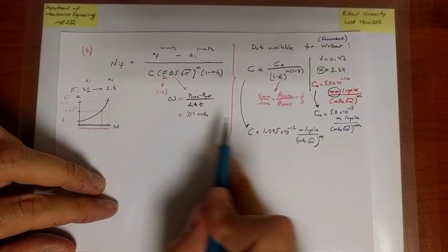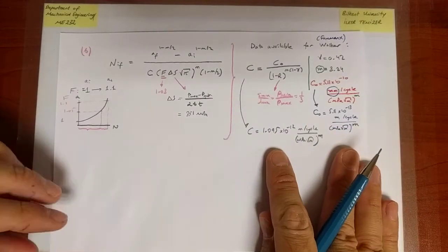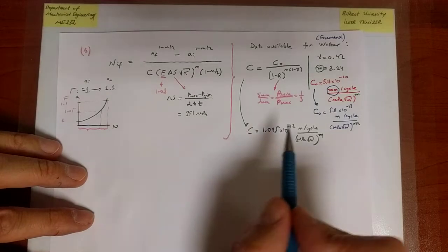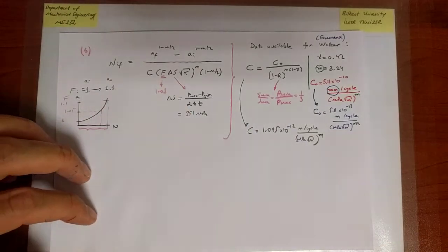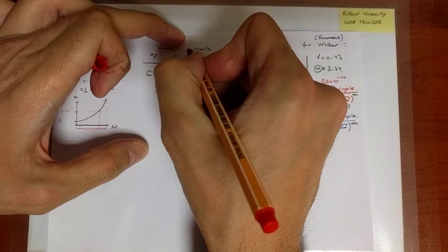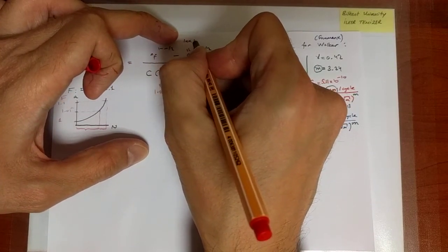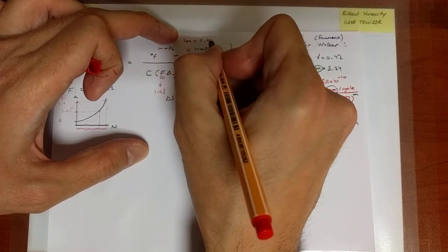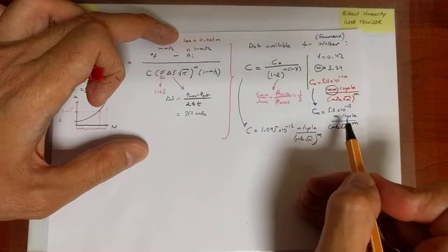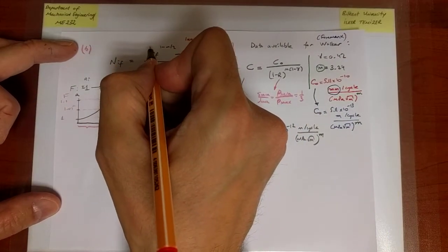Good. So now we've done everything. I know everything I need to. Material parameters, of course, there's nothing to memorize about that. It depends on the material, we just look up. But now I can go ahead and plug in the values of everything that I have determined. a_i is given. It was 1 millimeter, converted to meters, 0.001 meter. Everything should be in meters, right? The exponents and so on and so forth are in terms of those.